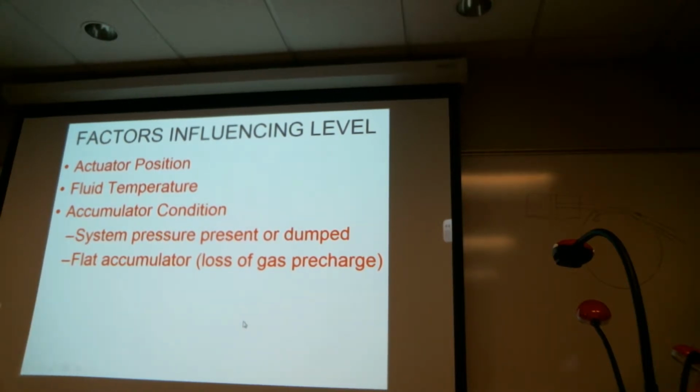So one thing you want to do is check before you service the reservoir back up. You want to verify that the accumulator has the correct gas pressure in it, and that you've not lost it. Because again, the volume in the reservoir is contingent on having an operable accumulator. So if you lose the gas precharge, that'll cause the level in the reservoir to drop.